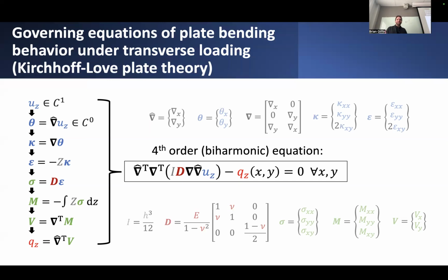Now, however, in the case of plate bending, this scalar field that we're looking for does have a definite physical interpretation, and it is, in fact, the transverse deflection field of the plate, varying potentially as a function of in-plane position within the plate. So we're looking for this two-dimensional solution, and you would visualize it as a three-dimensional plot, varying with in-plane coordinates x and y, and the actual height of this function uz would be illustrative of the actual deflection that this bending plate would undergo.